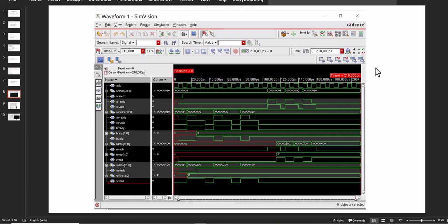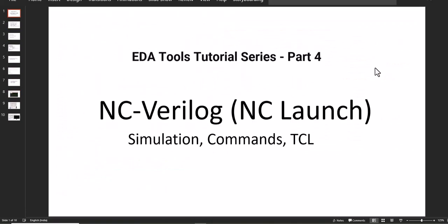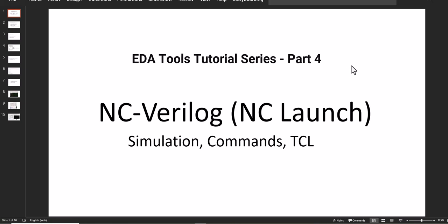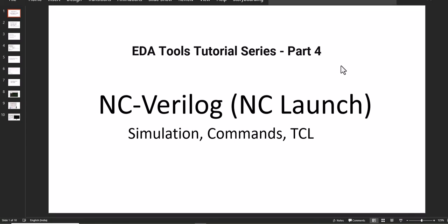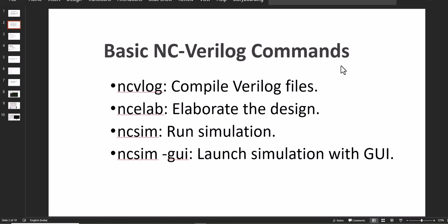On the presentation, this is the EDA Tools Series part 4, in which we are going to cover NCLaunch simulation commands and TCL file generation. The basic commands are very similar to VCS. Generally we need first compilation, then elaboration, simulation, and then the GUI launch, that is NC-GUI. The commands are simple: NC-VLOG, then NC-ELAB, NC-SIM for simulation, and the GUI.